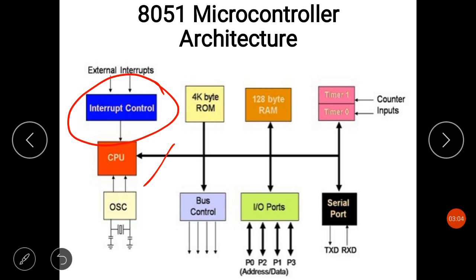Interrupts provide a method to postpone or delay the current process, carry out a subroutine task, and then restart standard program implementation. The 8051 microcontroller can be set up so that it momentarily stops the core program at the happening of the interrupt, and when the subroutine task is finished, the core program implementation resumes automatically as usual.